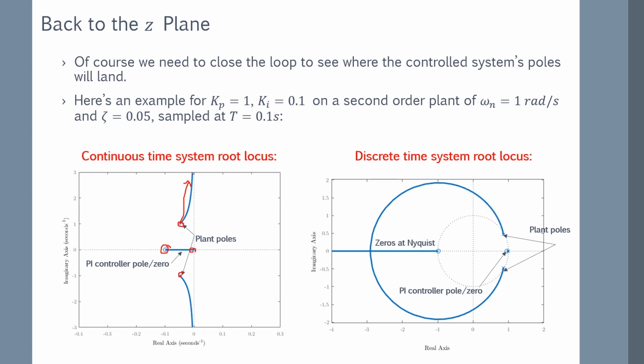As you increase the gain, you go along this line, and as you increase the gain, you go along this line. You see that the pole moves more and more towards the unstable part of the diagram, but never crosses the line. And this is what's important about this. It basically asymptotes, so it becomes less and less damped, but it never actually becomes unstable.